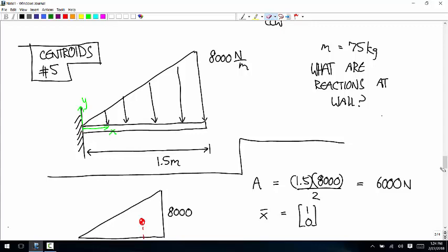Yeah. The way it is right here is more likely to break this connection than if that was flipped the other way. The reason has to do with the centroid. The area of that shape would be the same either way. But this way, the centroid is over here. If that triangle was flipped the other direction, the centroid would be over here. That means that in the other configuration, the moment arm would be less, and there'd be less of a couple required by the wall.